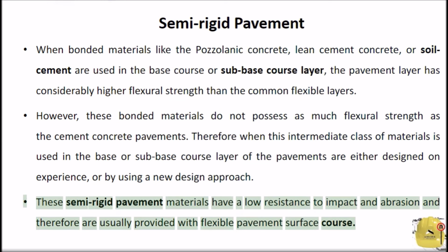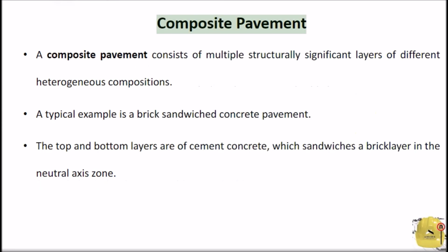These semi-rigid pavement materials have a low resistance to impact and abrasion and therefore are usually provided with a flexible pavement surface course. Composite pavement.